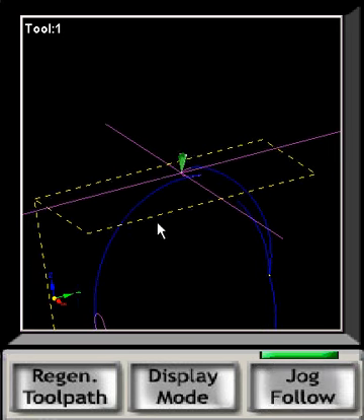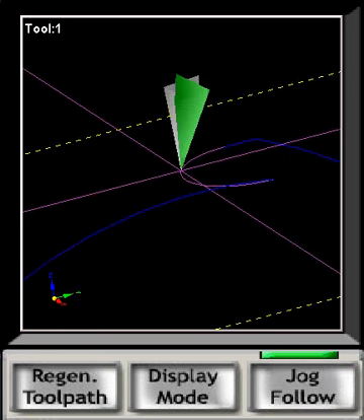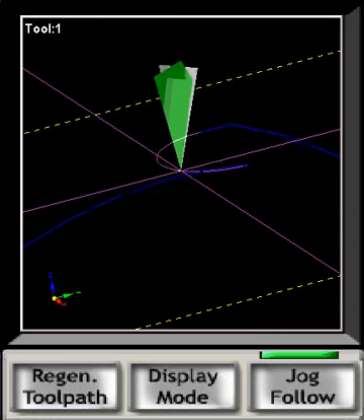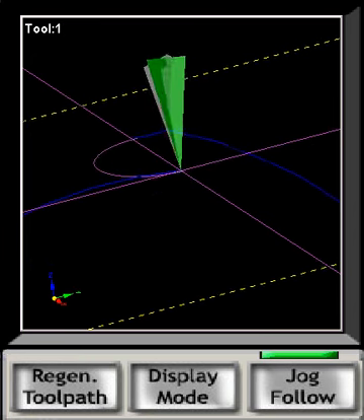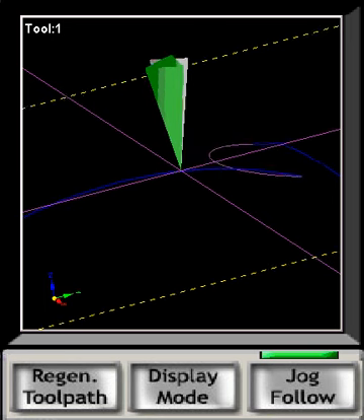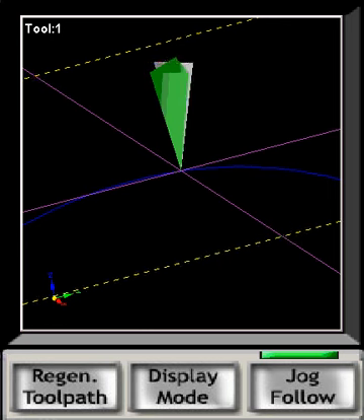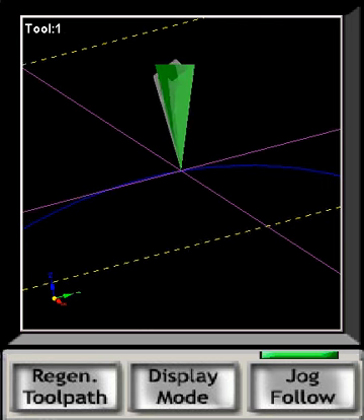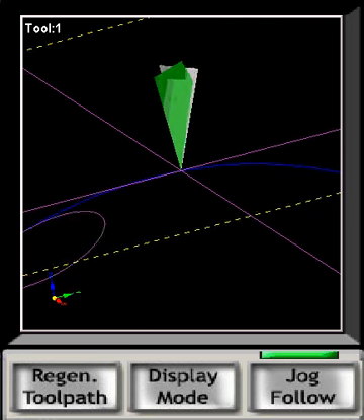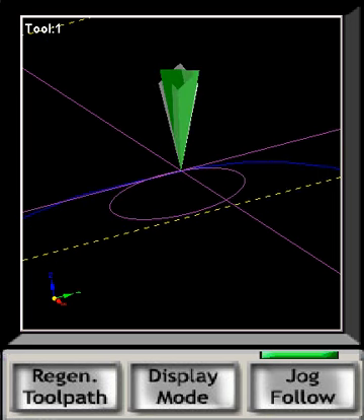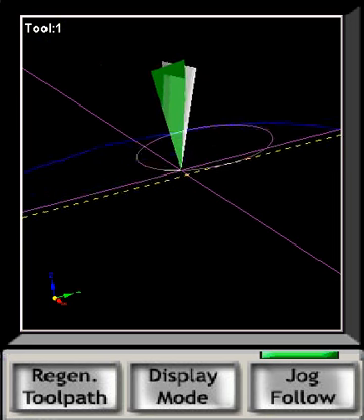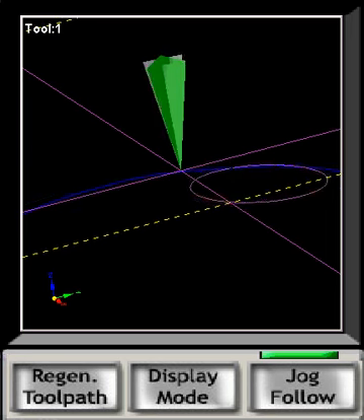and I'm going to feed hold and zoom us in on that so that you can see it closer, is that the tool head itself is rotating, because this is a 6-axis job. So the tool head itself is rotating to the appropriate vector to show you which way the tool would be approaching. This doesn't mean we do 6-axis toolpath compensation, by the way. This is just in preparation for it at some point down the road. Here you can see we cut a circle and tilt the tool as we cut the circle. And now we cut the rest of the way around the object.